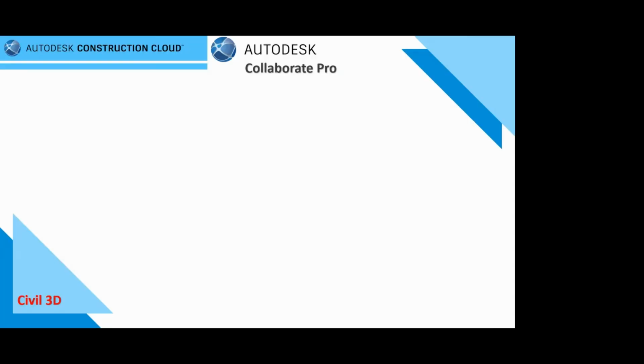And then when it comes to even more features with the Collaborate Pro version, we now have the handle to connect our Civil 3D model into the cloud and of course connect it to our Revit model. So Civil 3D links to virtually anywhere into Revit now from the cloud. It enables easy, secure, multi-firm concurrent authoring. So the idea here is I can watch my Civil 3D guys build up the topographical surface and then bring it into BIM360 and utilize that in my Revit model from the cloud.